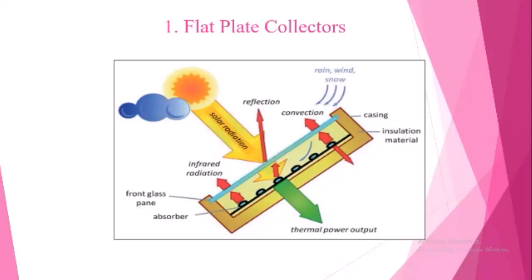Since solar collectors are not tracked and are installed at a fixed tilt, there is a loss of power collection equal to cos theta, where theta is the angle between the perpendicular to the collector surface and the direction of sun rays. This cosine loss varies due to daily and seasonal variation in the direction of sun rays. The collector glass surface and reflector surface collect dust, dirt and moisture. Thus, it requires daily cleaning. It also reduces the collector efficiency since the reflector surface gets rusted with the passage of time. Okay.